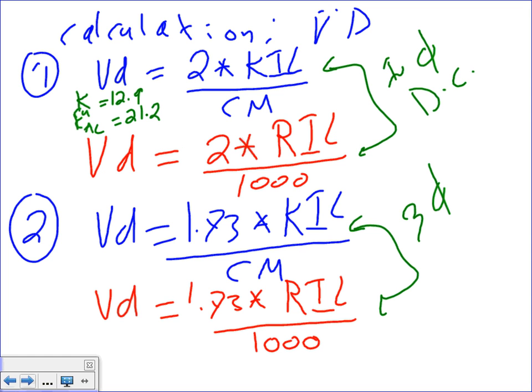All right, what's I? Muhammad, my friend, what's I? The current. What's L? The distance in meters or feet? In feet. What's circular mil? The cross-sectional area of the conductor. Okay, everybody, we established the criteria. Everybody knows what we're talking about here.